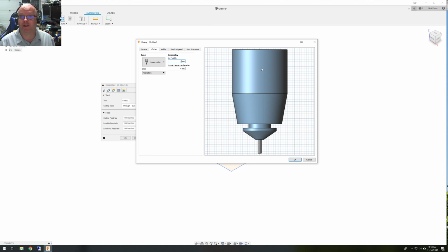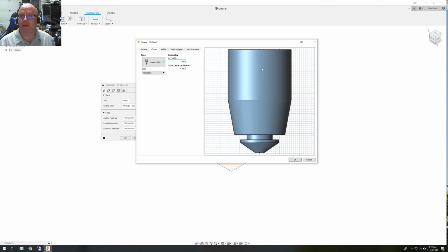But when it gets focused, it's actually down to 0.1. I get a 0.1 beam out of that thing. Sometimes a little less, sometimes a little more, but 0.1 when I do tongue and tab and slot fitting, that setting works great. I get great fits out of it. I never have to sand. Occasionally I have to wedge a little bit, but I prefer that.